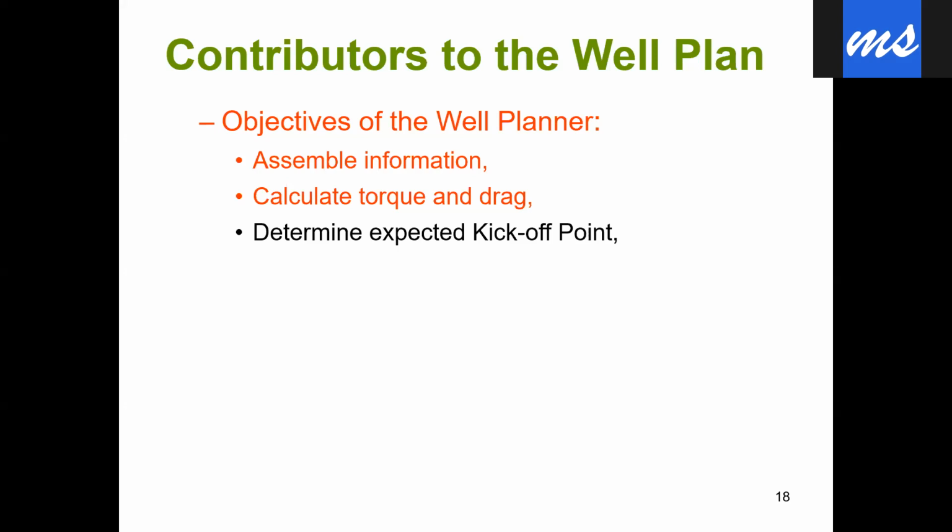So what's going on with azimuth? We have a phenomenon they call walking to the right. The well, or the BHA, will tend to create a change in azimuth in the direction of the right, because normally we are rotating to the right when we are drilling.